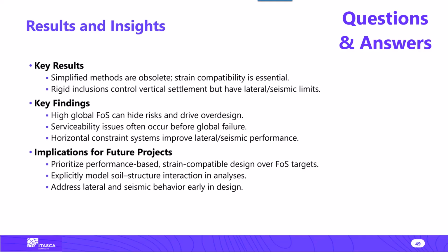Great. Couple more questions. When should I consider that Qa, the asymptote, is equal to Q failure, Qf, in the stress-strain curve for hardening soil? Oh, okay, so that is controlled by the failure ratio, Rf. So all those parameters are somehow connected, okay?